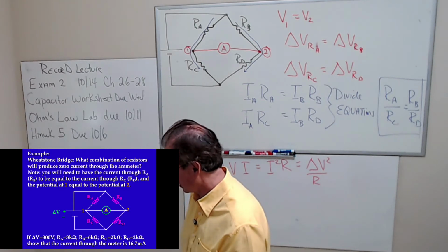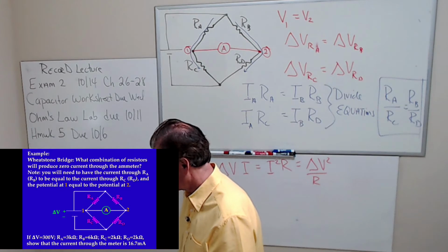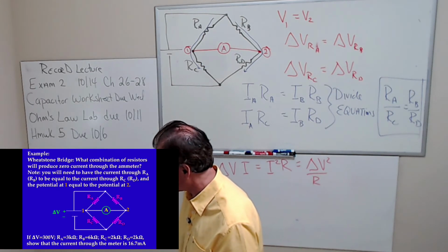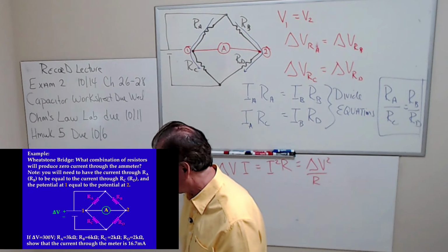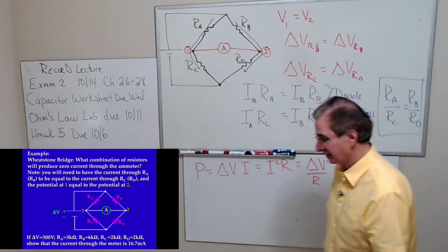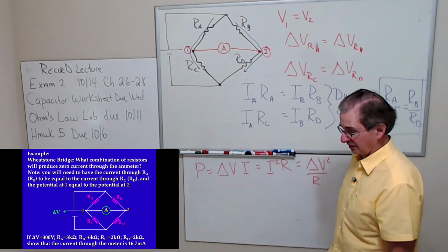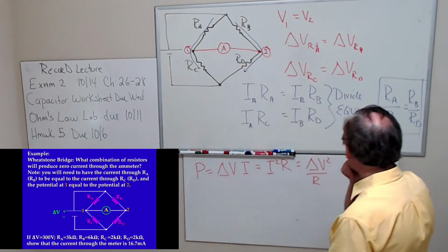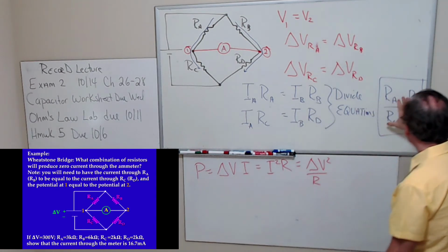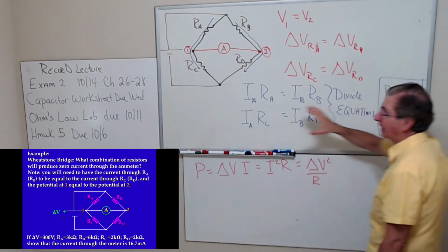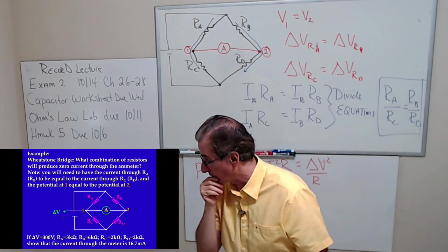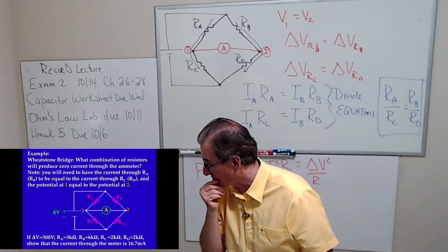The wire can't measure anything. That's the only difference. You're right, you can put a wire there. You can treat it like there's a wire there. That's true. It acts the same, it's just that the wire doesn't measure anything. Okay, so this is the condition, and you can use this to measure resistance. And yeah, this really should be a galvanometer.